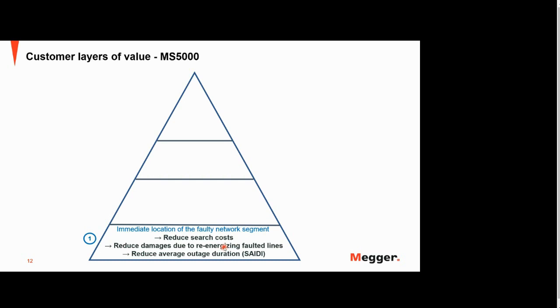There's always a 5 times improvement in your SAIDI and SAIFI. The analytics and predictive maintenance options in the MetroView software help you identify the weak spots in the grid, like broken conductor, recurring arcs, high impedance faults, missing phase, harmonics, etc. Everything can be detected with the MS5000. Once you know whether you have weak spots in the grid, your team can do very early stage maintenance.